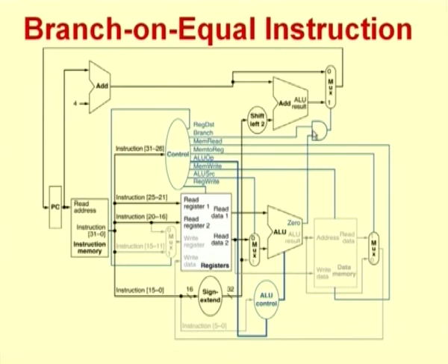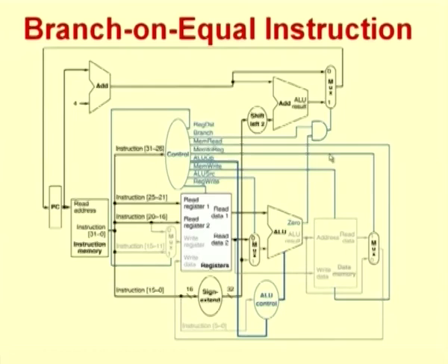If it is not a branch, that means I will go to the sequential instruction. So that control again will be selected in this multiplexer by this kind of a signal. You can see we added one AND gate here to do that. Similarly, this control unit and this ALU control logic will be full of such logic gates in order to come up with this. Okay, so this is how the different operations are carried out using this kind of enabling of different elements in the data path.